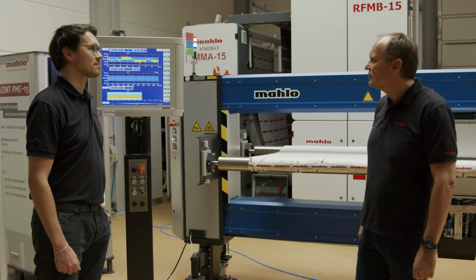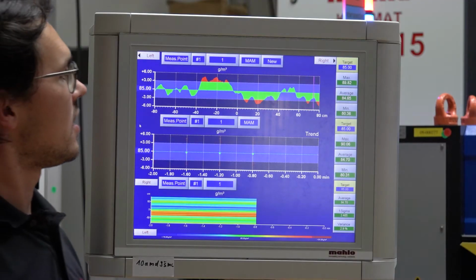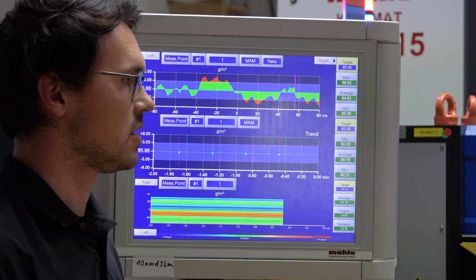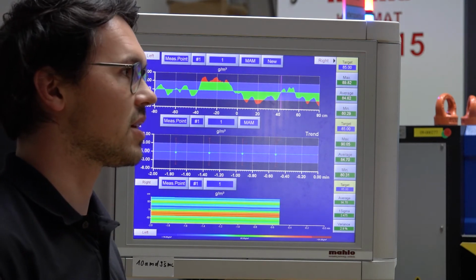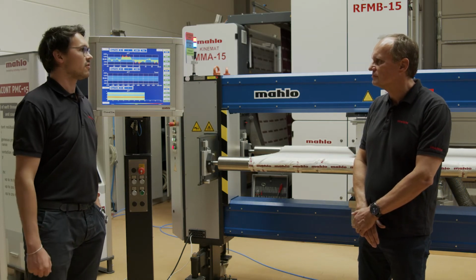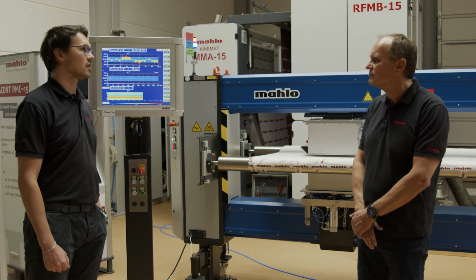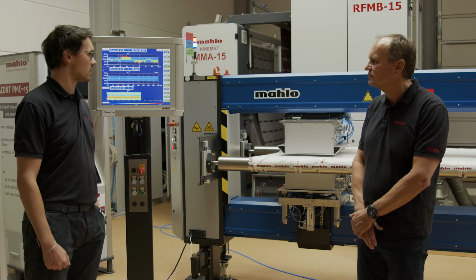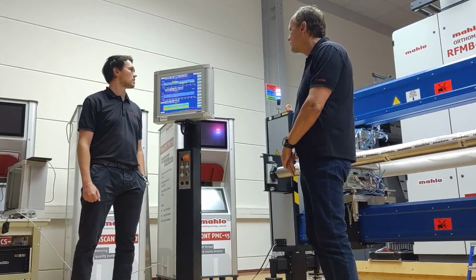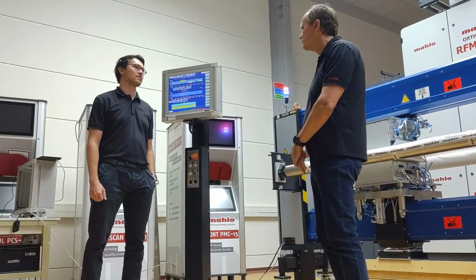And what is the red color in the cross profile? The red color shows me the result if some weight is out of tolerance. So every customer has a tolerance for their product, and here you can easily see at one fast view during production that maybe in some areas of your product the tolerance isn't that good, so that you can reach a 1A product, and therefore you have a very fast shown result and can adjust or react.